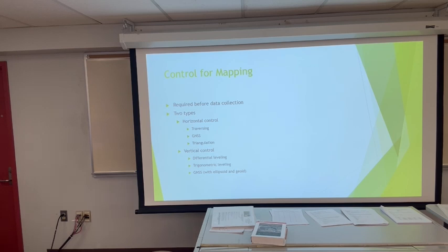Then you can apply, okay, if you're set up on an elevation, add your HI, your instrument height, shoot however far over, and subtract that vertical distance, and then subtract the rod height. You've got the elevation of your next point. So a lot of times if you are doing traversing, you will do all of that at the same time. The GNSS,